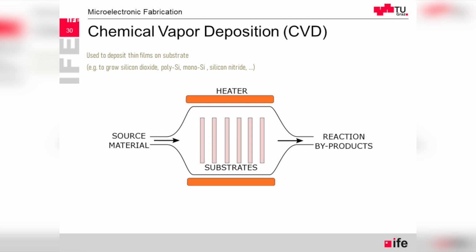One more feature that is really nice in this process is that we can handle several wafers at the same time. What you can see also here on the picture, there are several substrates. Even if it takes a long time, because of putting it to a certain high temperature, and the gas is introduced at a certain speed to control the process, maybe it will be very slow. But despite the length of the process, the handling of several substrates makes it much better.